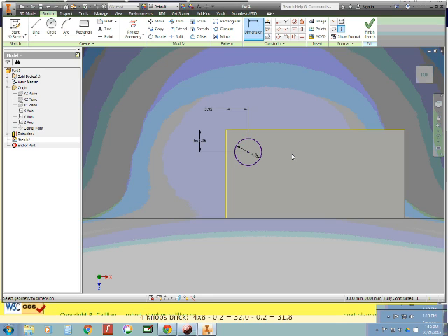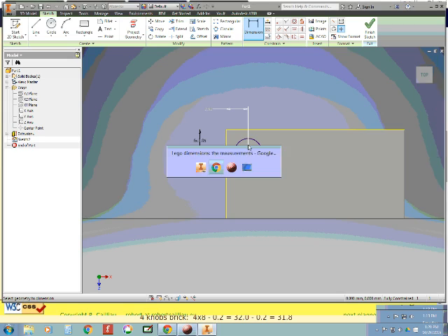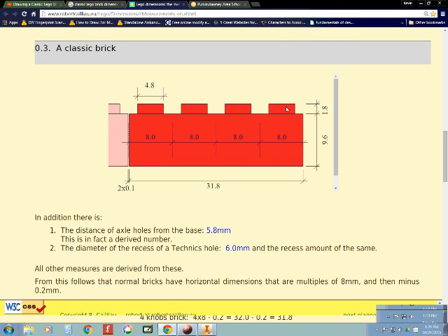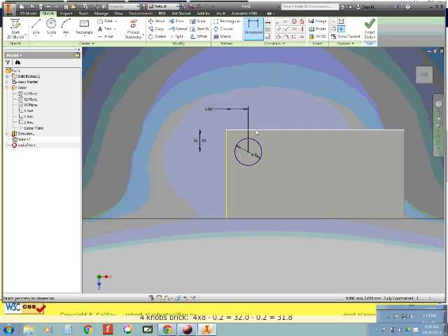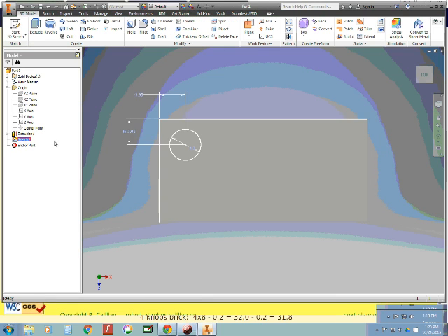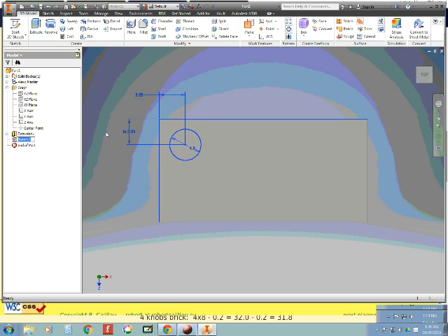Now there's a couple ways I can proceed from here. I can either make a rectangular array of this geometry and then extrude it to get this height, or I can extrude it first and then make the pattern. And one of the rules in creating Inventor files is always keep your sketches as simple as possible. So it's going to be pretty hard to make this any simpler than just a single circle. In fact, let's go over here and rename this sketch. Oh, we got to finish the sketch first and then name it, if it'll let us. Knob sketch.